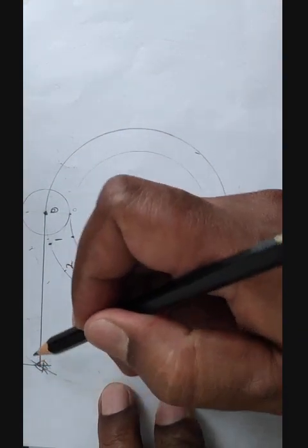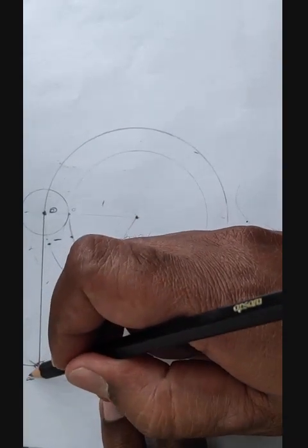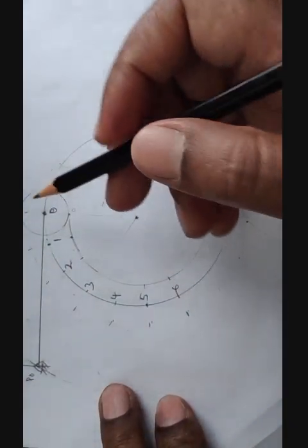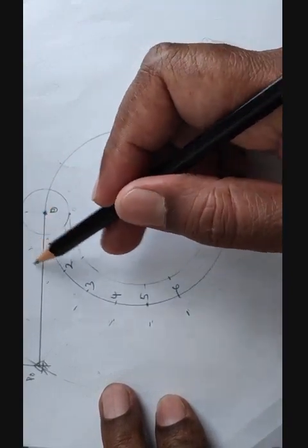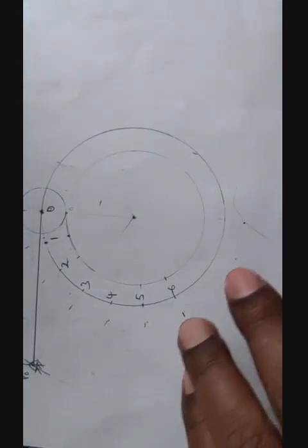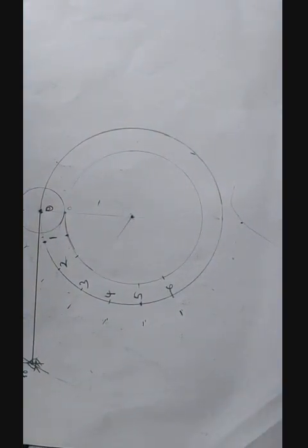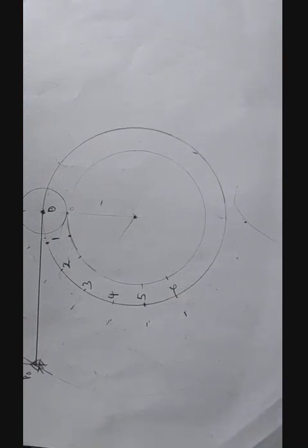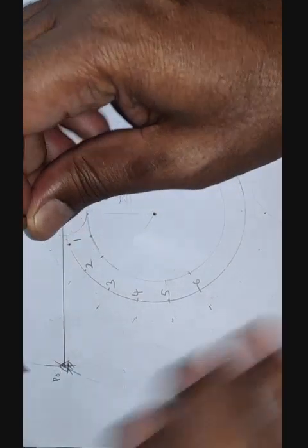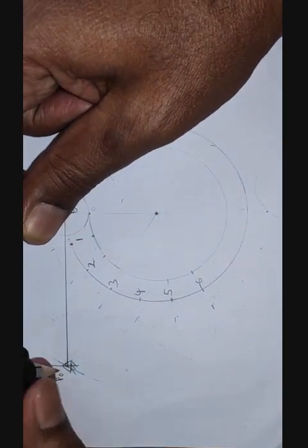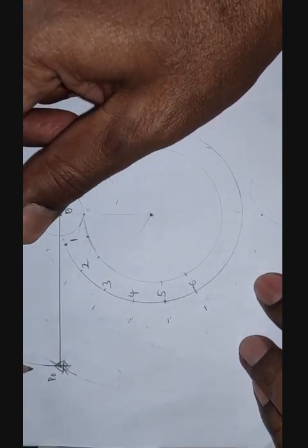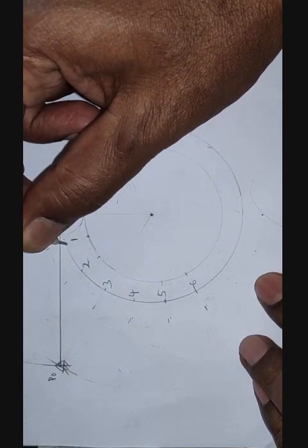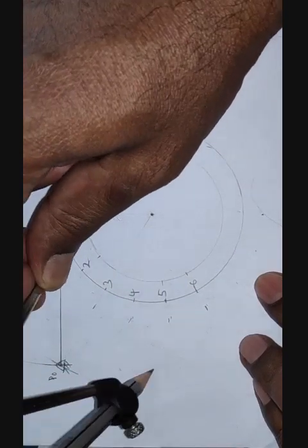I can refer to this as the pivot. So let me name this pivot P0, because this refers to 0. And if there is no lift, as this roller comes here, where will be the pivot? The length of the oscillating lever cannot change. Therefore, you measure the length of the oscillating lever, which is 70 mm. So when the center of the roller comes from 0 to 1, the location of the pivot should be here.